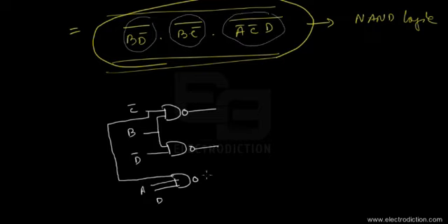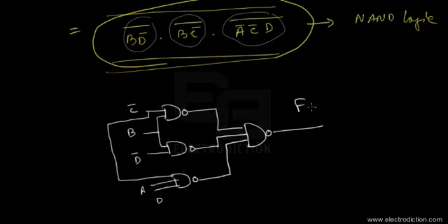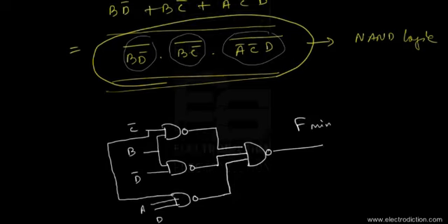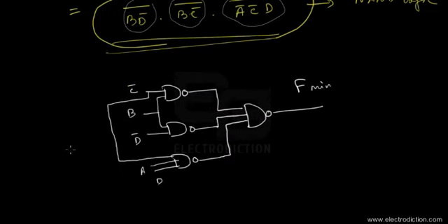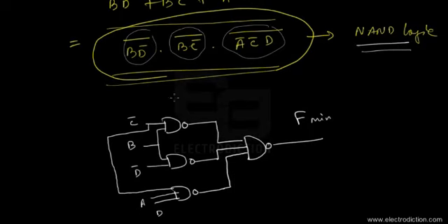We're going to take each of their outputs, and we can see that these complementary values have again been multiplied with another complement. So it's quite easy to understand that the outputs of each of the gates just need to pass through another NAND gate so that we can get the result. Whenever we do this, we finally obtain our required expression. So we get this expression F min using the universal logic, the NAND logic that we have used to construct the circuit.